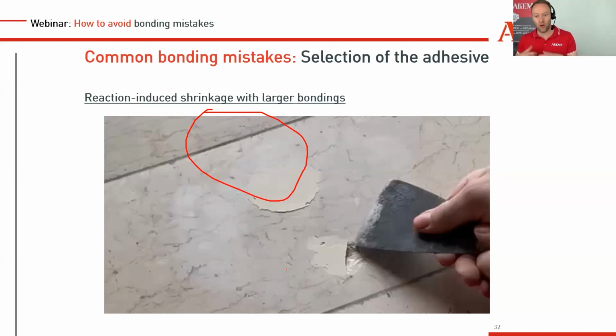When you do repair work and you have a spare piece of stone, crush it, make small particles out of it, 2, 3, 4, 5 millimeters. Throw it into the glue and use that then for filling. But when you do that, first mix the two components. Put the hardener and the polyester, or put A and B together when you use epoxy, for example. Mix all the components, then throw your stone particles in it, and then you can start filling the big holes, and later on the grinding and polishing.